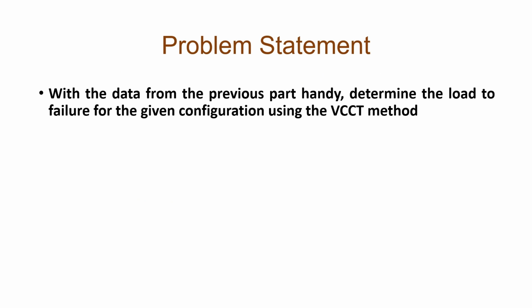This part of the question asks us, with the data given from the previous part, which is essentially our K1C value, to determine the load to failure for the given configuration, a configuration that we're going to get to in the next slide, using the VCCT method in ABAQUS.